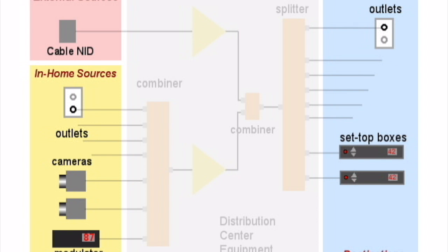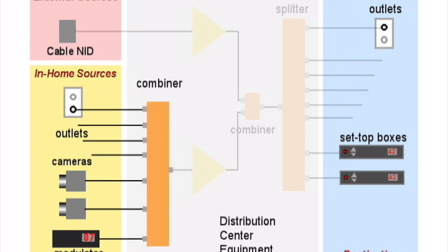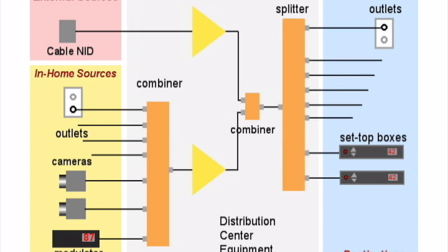First, show all the external service inputs. Then, based on the equipment list and plans, determine the total number of in-home sources and jacks and the total number of external devices and jacks you need to support. All internal coax runs are combined into a single internal source that contains all the modulated channels. Depending on the number of inputs, the combined signal may need to be amplified. The external source is also amplified, and the external and internal signals are combined. The result is then split as necessary to support all the external cable runs. Almost all residential distribution systems will be some variation of this design.